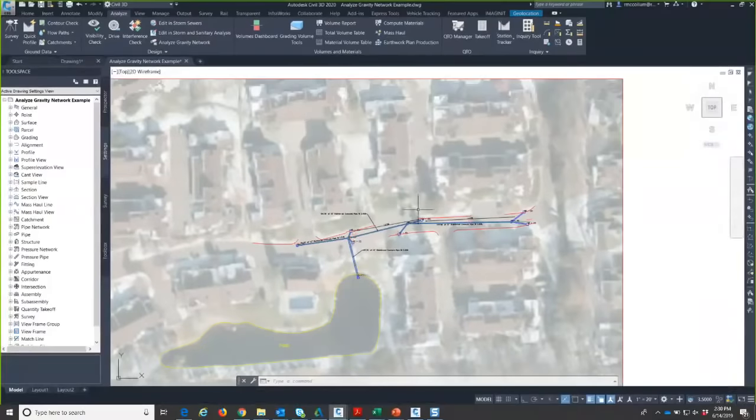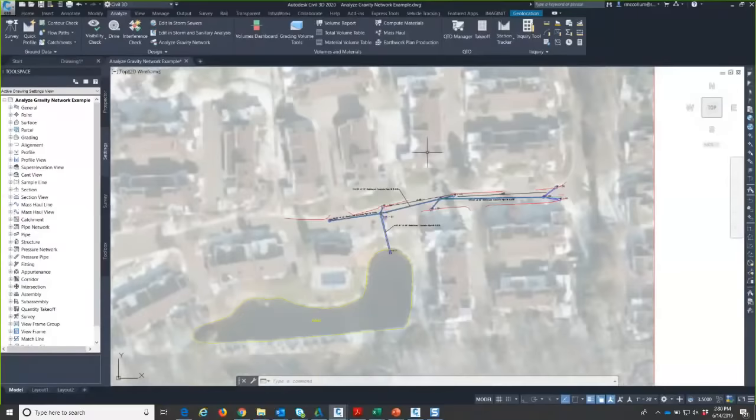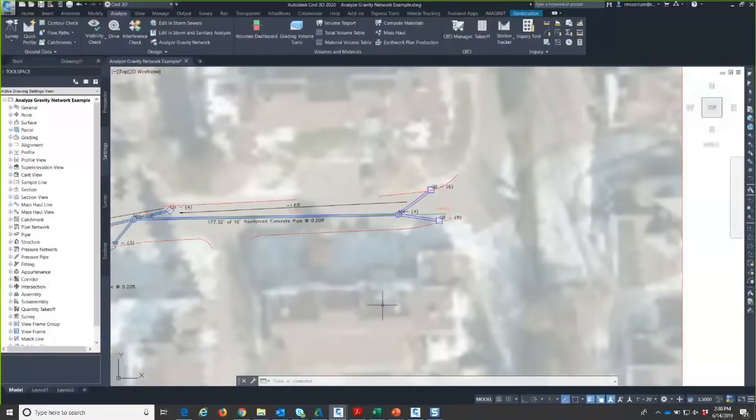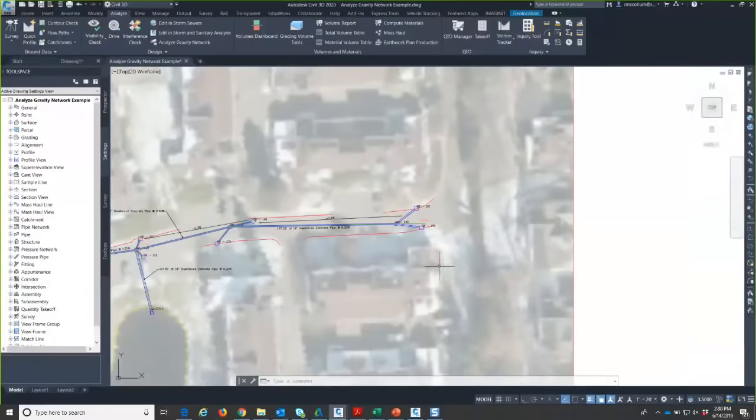If you are using catchments, you can solve for the time of concentration using the TR55 method and the surface, or you can put that concentration in directly. And then the Q, I should say, for that is based on the rational method. So it's nice, it's quick, but it might not be what you need. You might need to use, for some reason, a different standard than that.